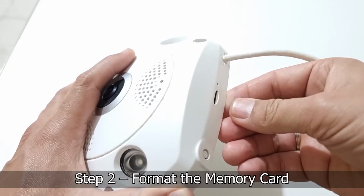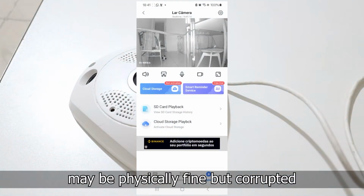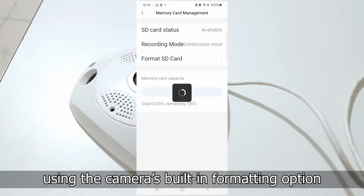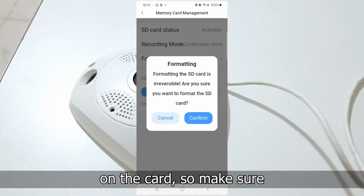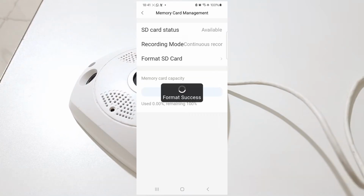Step 2. Format the memory card. Sometimes the memory card may be physically fine but corrupted. In this case, format the card using the camera's built-in formatting option or a computer. Important: formatting will erase everything on the card, so make sure there's nothing important before proceeding.